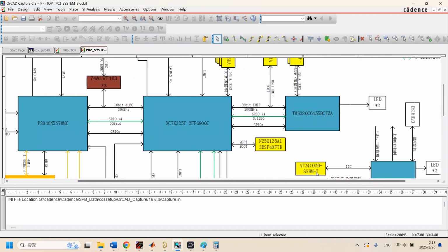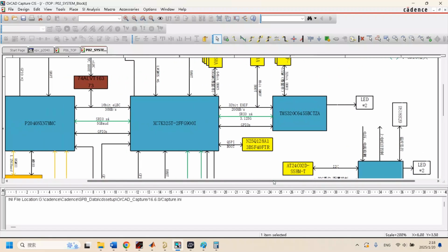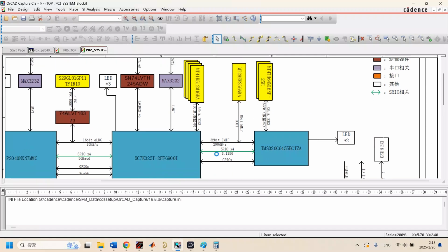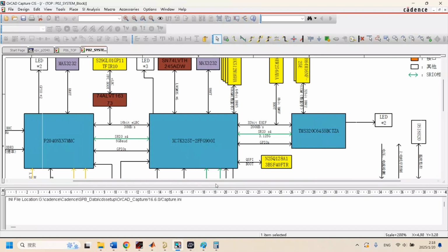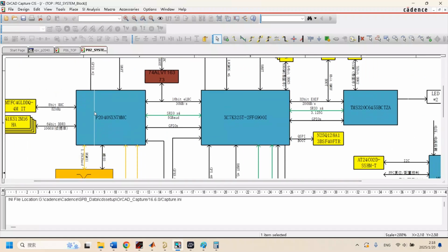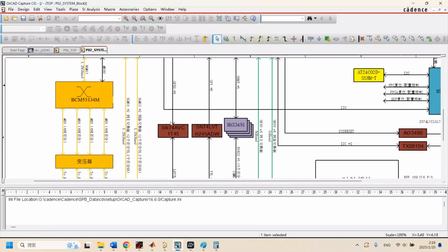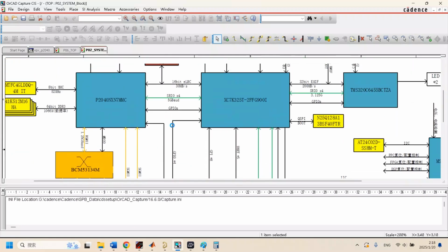After getting the raw data of the picture from the targeting pod, it can send it to the DSP to reduce the space of the graphic data, then send it back to the FPGA and send it to the CPU. That's what we do in modern day. That's the design we're doing in the modern day. So that's typically the data bus for the modern design.